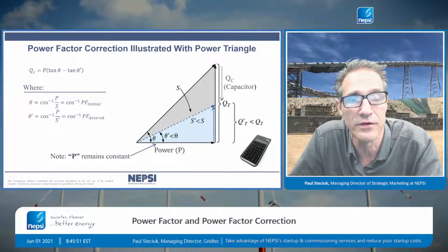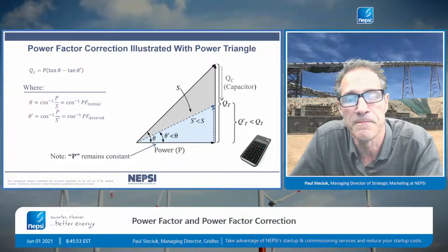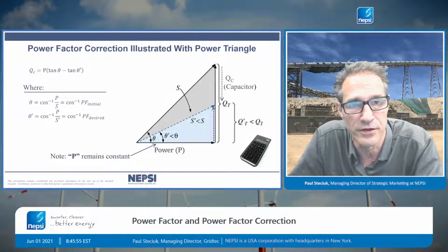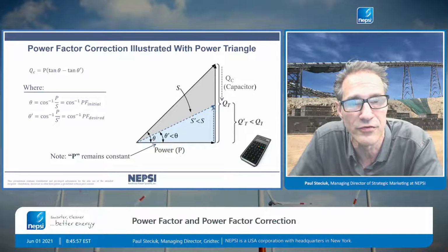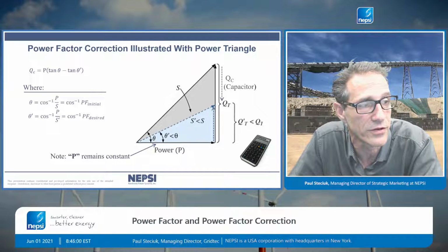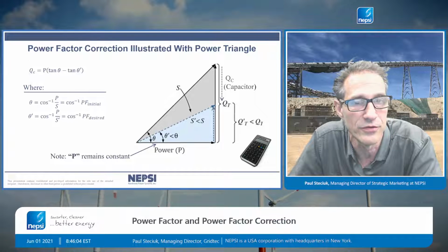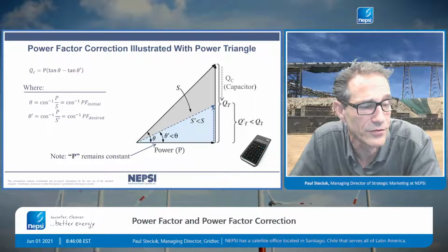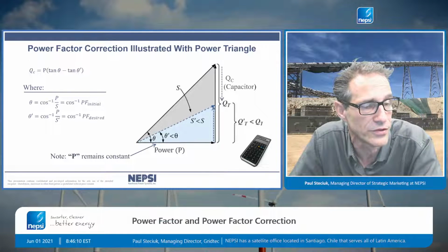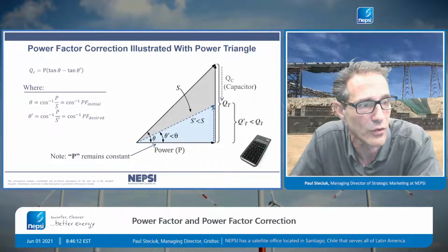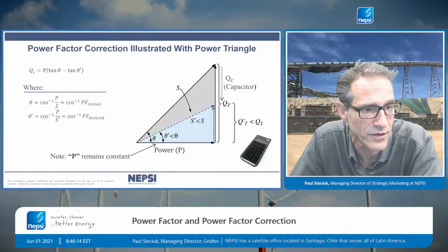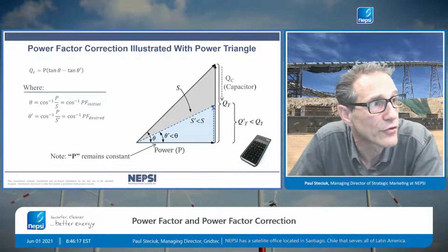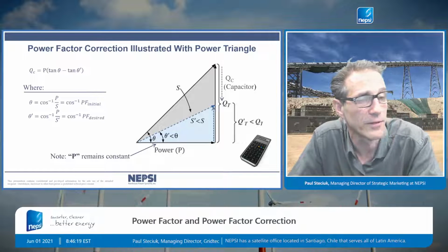We do have industrial and utility customers, and utilities in the United States. There's a good couple hundred electric utility providers in the USA, and many of those utilities do not have power factor penalties at all. Sometimes you get an engineer who wants to justify the purchase of a capacitor bank on loss reduction, and it just doesn't happen.